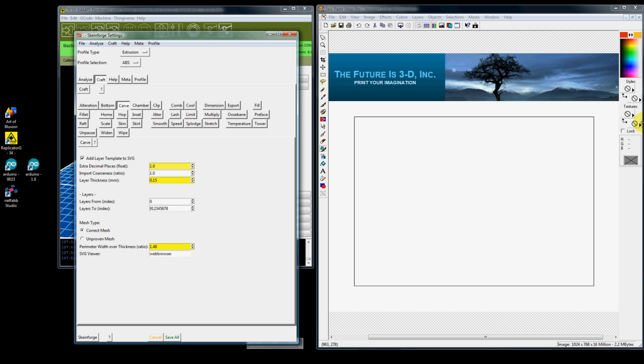My name is Jeff Christiana and this is video number 4 of the Skeinforge 47 video series on how to use Carve. Carve is a very important setting. What Carve does, and we're going to go through each one of these layers, is set your layer thickness. I'm going to be covering in a lot of these modules things that you really need to know and other things that are not really necessary. If you do need to see what these other options are, then click the question mark and that will bring up a help screen to help you through.